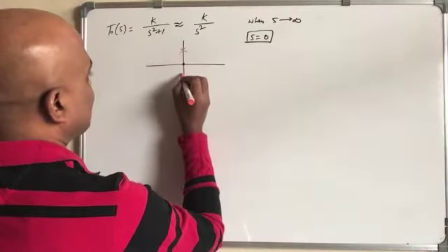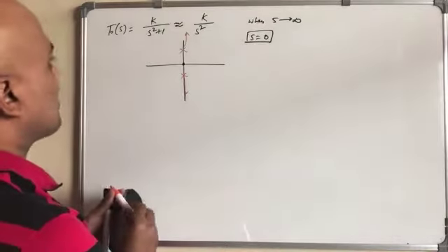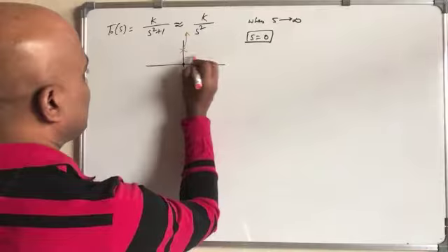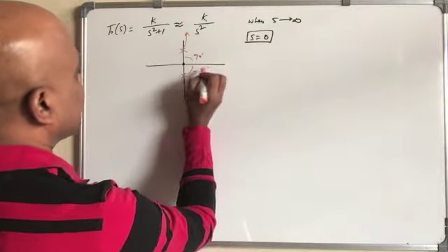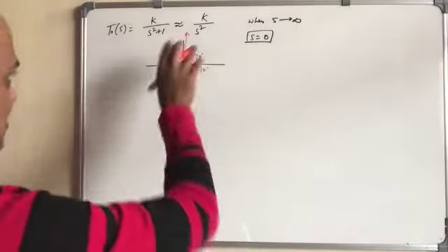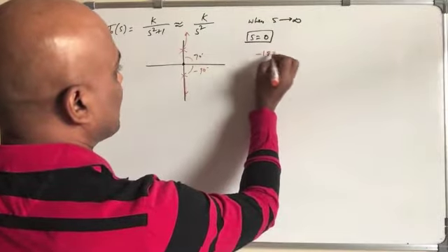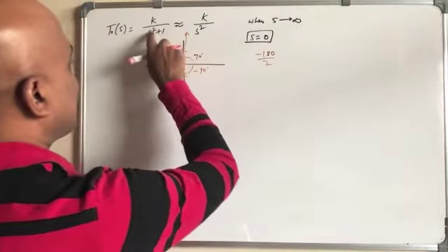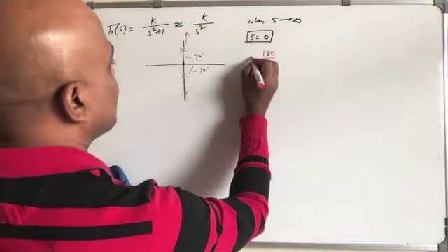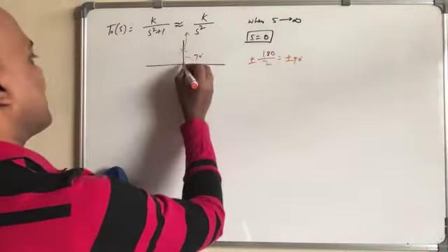And we know that these are the poles, and hence it will go upward like this, and the value will be 90 degree and minus 90 degree like this. That we have seen earlier also. So minus 180 degree divided by 2, because there are 2 here, n, so hence you get plus minus 90 degree, and this meets here.